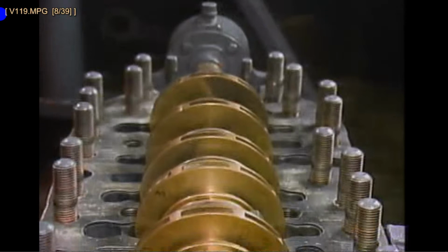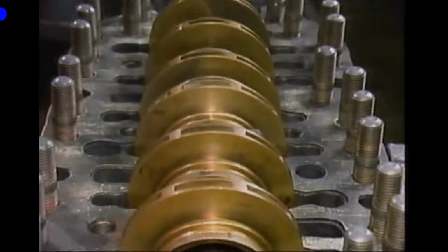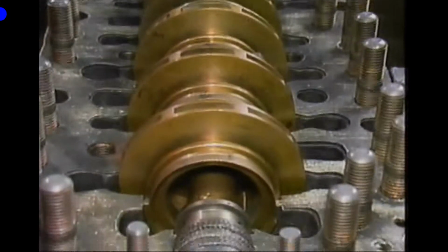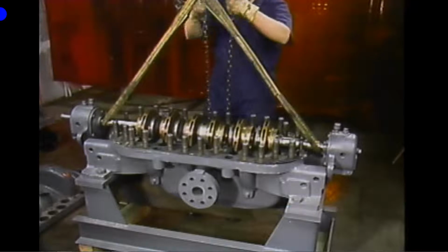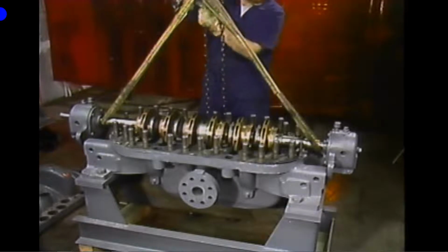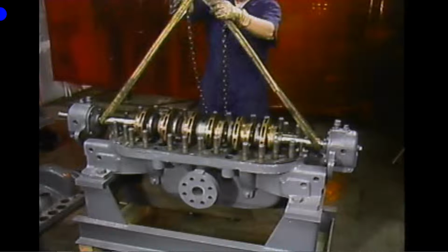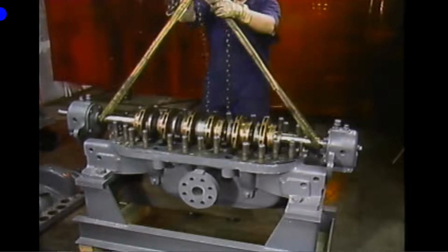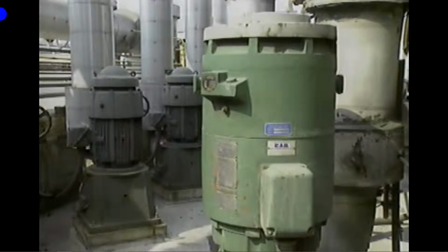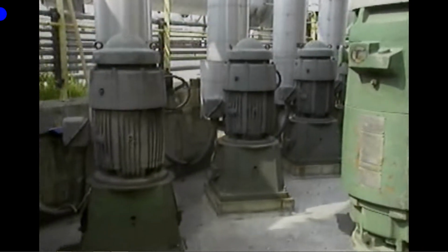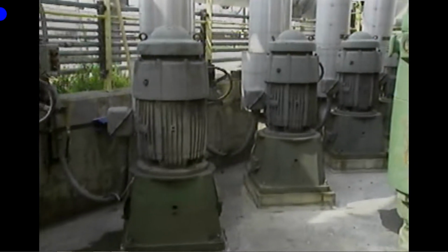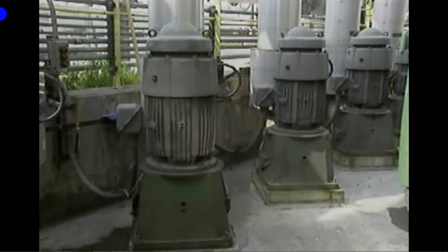Equipment that includes a number of rotating components may have more than one critical speed. For example, this shaft assembly has several critical speeds. It could be dangerous to operate this shaft assembly at any of its critical speeds. However, the operating speed of some machinery cannot be controlled. In these cases, the machinery is normally designed to operate at speeds other than the critical speeds of its components.